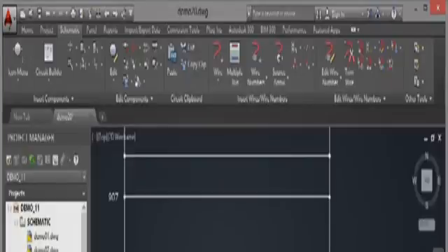Now be careful. Can you see that my object snaps are on? So what I need to do there is actually physically turn that object snap off. So let's turn that endpoint snap off and come back into the drawing. And then I hover like this and I just click on the line there. And it will place a rung dead on where it finds that location marker, that 908. If I do the same here, click there. Can you see it already lines it in with the location marker for me? It's very, very clever, AutoCAD Electrical. It picks up that piece of text and knows that that's where the rung has got to go. No object snaps needed, you'll notice.